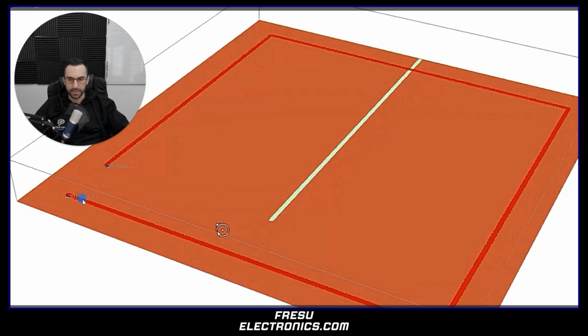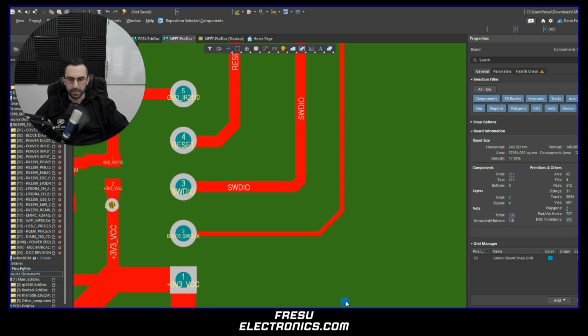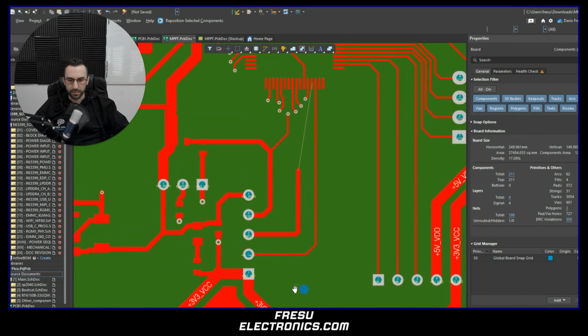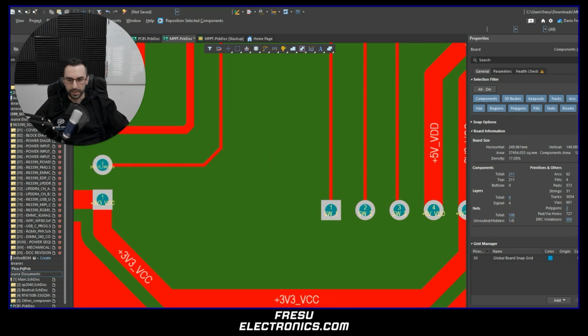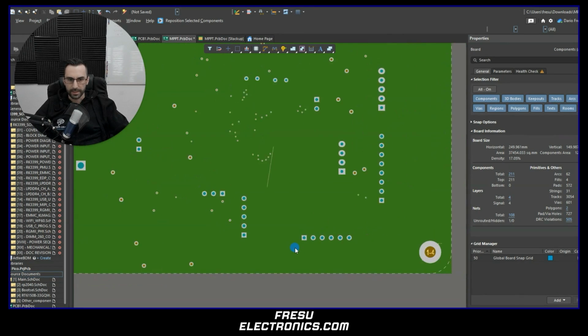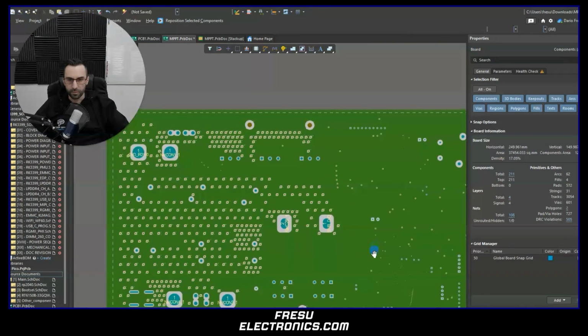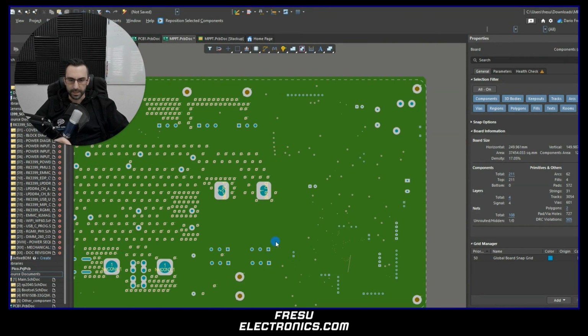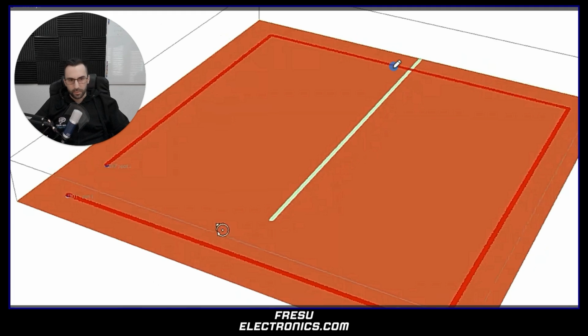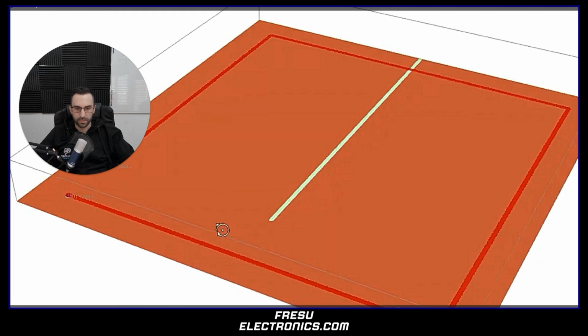So we still have the signal trace, which goes all around this plane in there. But this time we cut the return reference plane. And this is what we see in many designs, that sometimes we have a signal layer on the top and then the bottom plane has some cuts. So it's not full like in this case, but it has some cuts in the plane. But now the problem is what happens when we cross this split of the planes with a signal trace. And this is exactly what this simulation is going to show you.